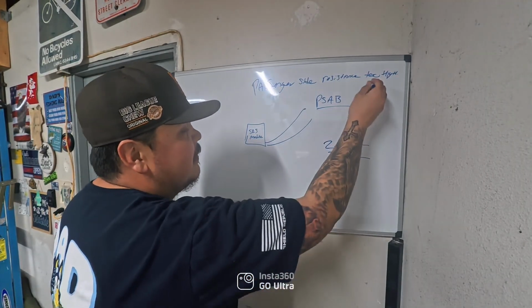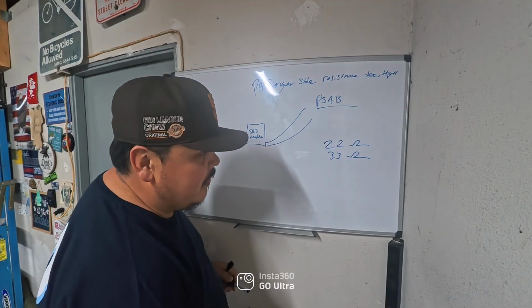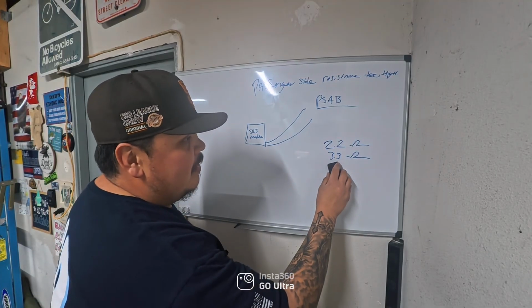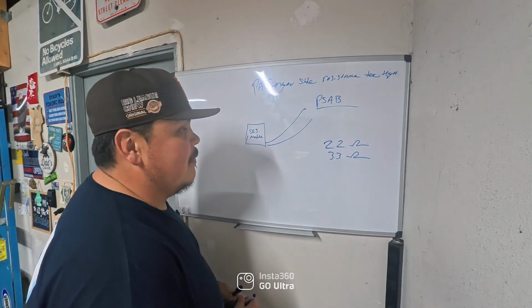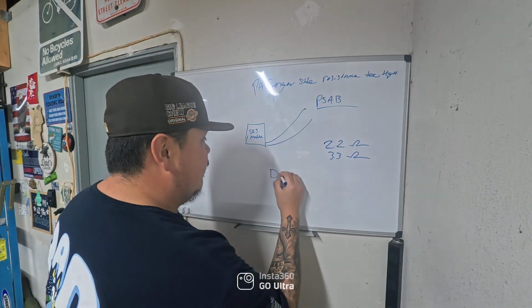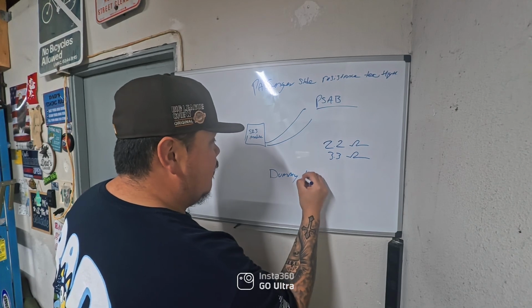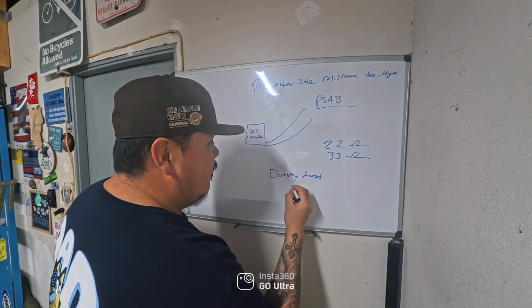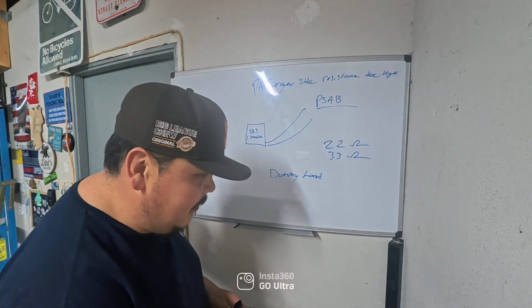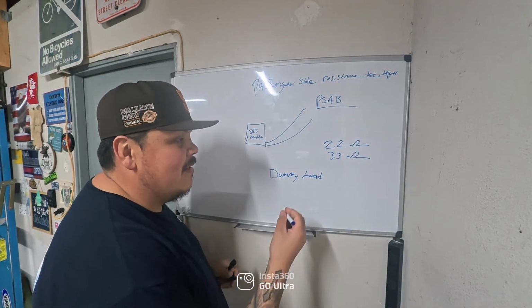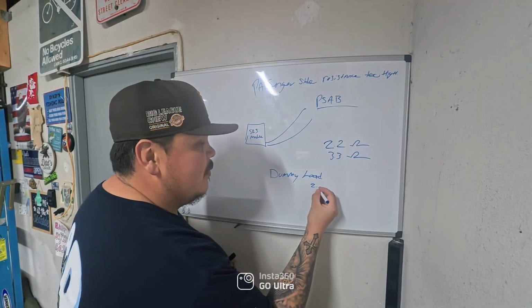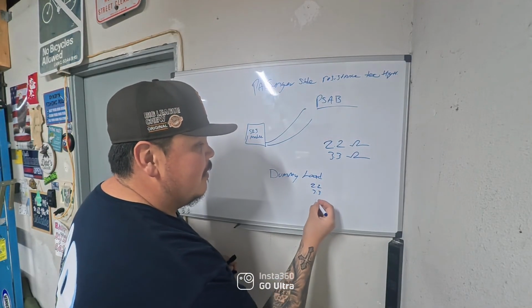When the airbag becomes faulty, usually on your live data you'll see that it will show open or the resistance will be super high. The dummy load is just a device that has a resistor inside. You'll have two options, 2.2 and 3.3 ohms.